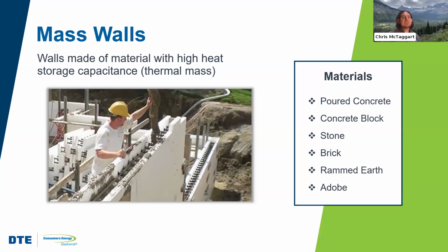But basically, stone or masonry type products have more ability to store and then slowly release stored heat energy. So they act as a buffer. They're not insulation, but they're more of a heat sink and storage mechanism, so that maybe you don't need quite as much insulation.